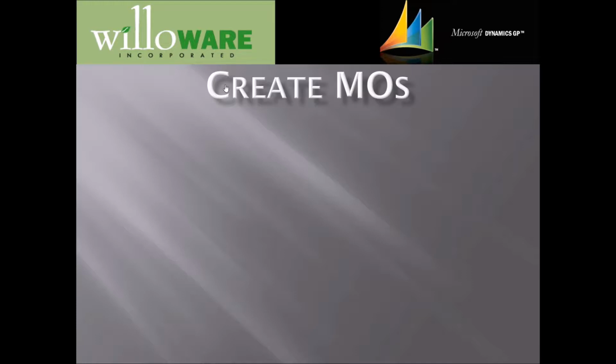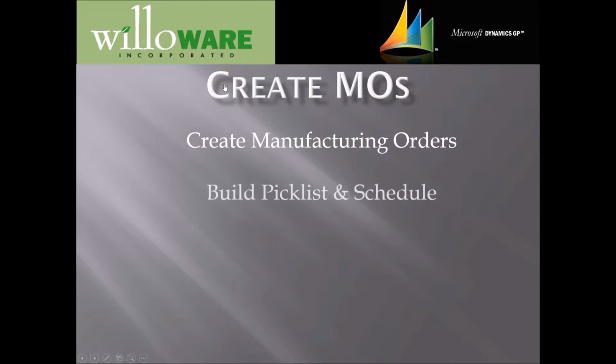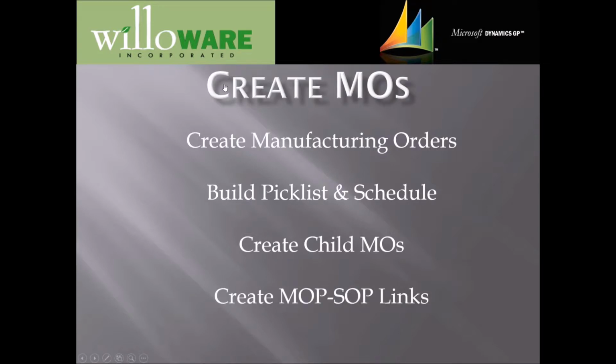If the MO status option is set to released, and manufacturing setup specifies that inventory should be allocated when the MO is released, MO Gen will also create a component transaction entry allocation transaction to allocate the components on the pick list. When the Create Child MOs option is marked, MO Gen will create child MOs for each of the non-phantom subassemblies on the pick list of the parent item. The Create Child MOs process continues down each level of the assembly until there are no more make components. This utility can also create a MOP-SOP link between a manufacturing order and a sales line.